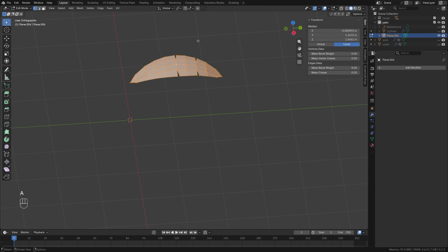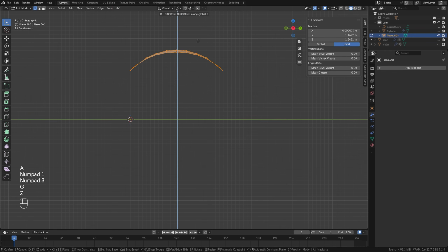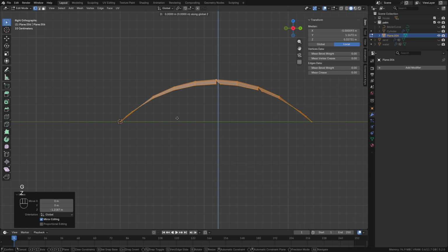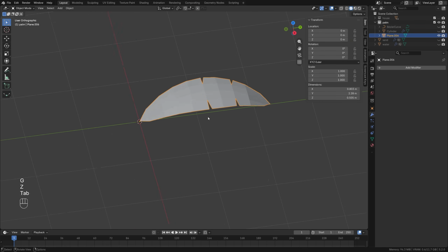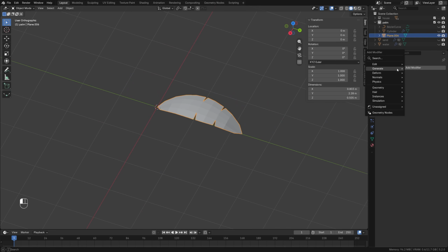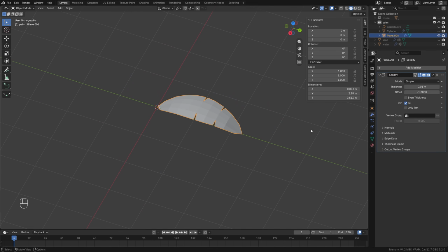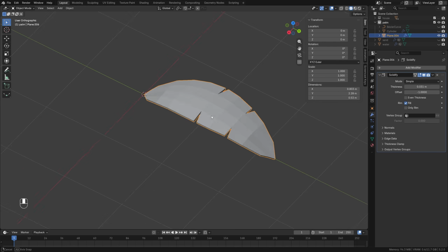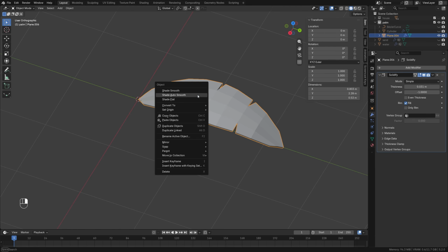After this, we turn off proportional editing and on the same side view, lower everything down. We keep the center here in the corner. Further, for us this will be very convenient. And here it is, the basic shape is already present. Now for the leaf, we add the Solidify modifier to give it thickness. We adjust it, again for now by eye. Later, when the whole palm is visible, it will be possible to adjust this.